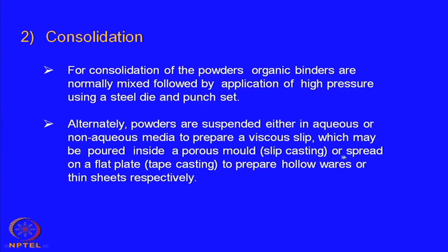So, particularly for preparing hollowware like a cup or a vase, or even sanitary ware, it can be made by slip casting using a porous mold.